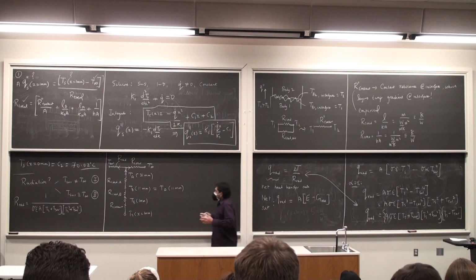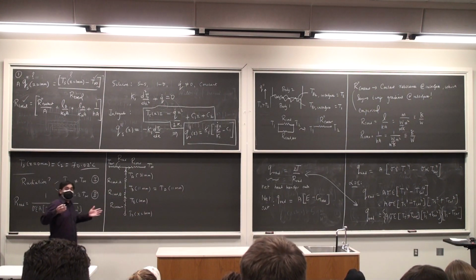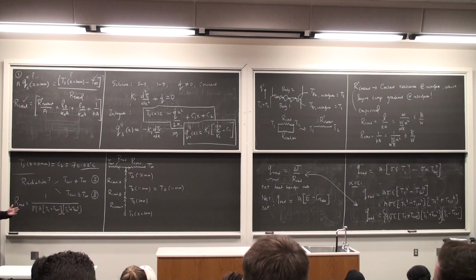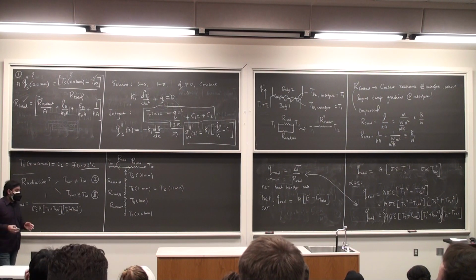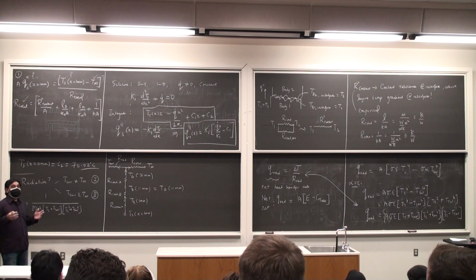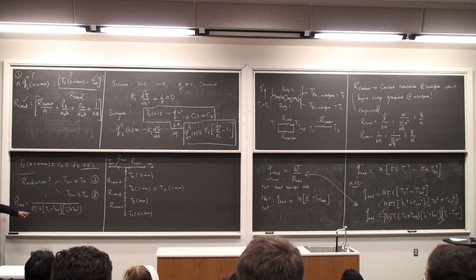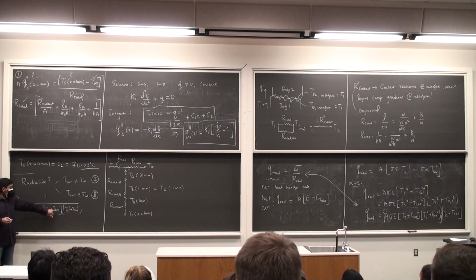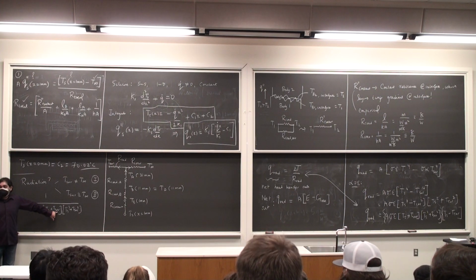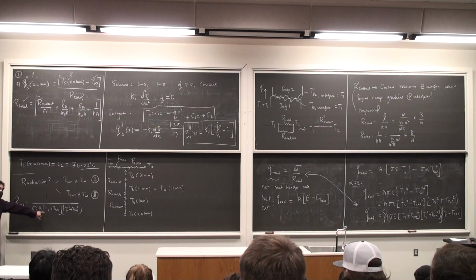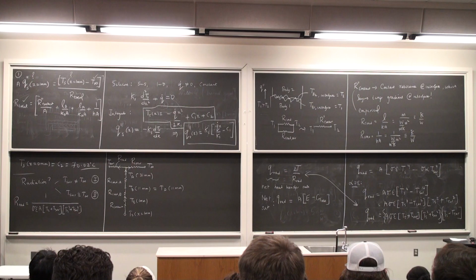Here I depend on the type of the surface, which is epsilon, dictated by how rough the surface is. Is it a polished surface? Is it a diffuse or a specular kind of a surface? Emitter, we'll see all these terminologies soon. Depends on the area. Unfortunately, depends on the surrounding temperature, which would be unknown to me. Depends on the surface temperature, which is just something that I could be solving for really.